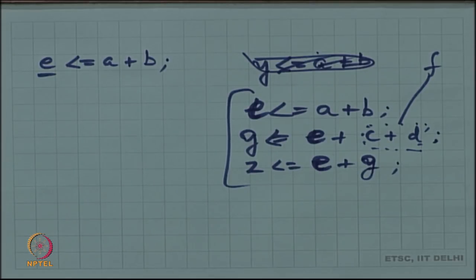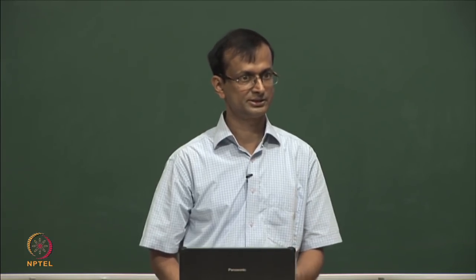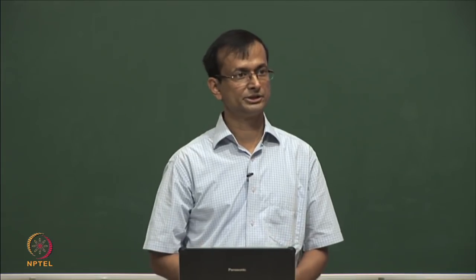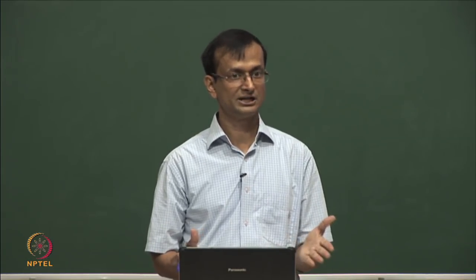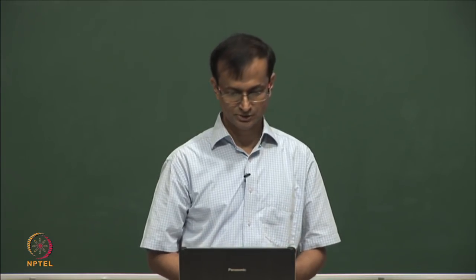It is just some temporary variable that the synthesis tool has internally created. That too needs to be stored. So, I have variables that are either explicitly declared or they are implicitly inferred. If you have a complex computation all as part of a large expression, you need to break them down into smaller units, some of which may need to be stored.